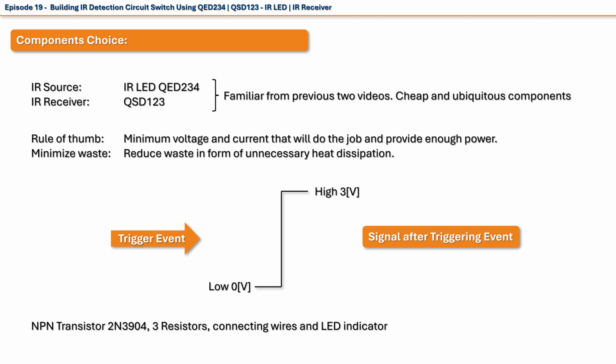Since our design will use an indicator LED that has a voltage drop of around 3 volts, we must go a little bit higher than that, so our next best readily available choice is 5 volts. The choice of 5 volts will satisfy requirements for the voltage drop of the indicator LED. Also, it will provide the necessary bias voltage divider for the detection circuit, and at last, it will provide enough voltage to bias and power on all other components in the circuit.